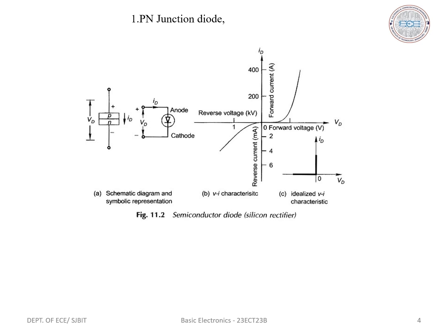As we increase V, the barrier potential Vj keeps reducing. At a certain voltage, V will overcome the barrier potential and the current will begin to flow. With an increase in forward voltage, the width of the depletion region reduces and eventually the depletion region will collapse.